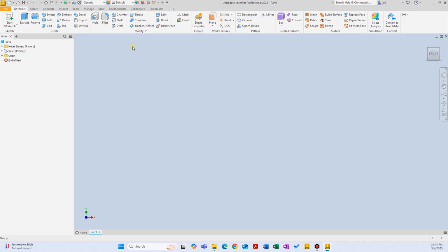Because if you apply a lot of modeling actions and in between you add a bunch of fillets and chamfers, and if you have to go back and modify anything in those features, then those fillets and chamfers may not be applicable anymore. The projected geometries may not work the same way, which would cause a lot of problems, and then you would end up having to go back in the browser tree and find where the problem occurred and spend a lot of time troubleshooting. So that's why always try to finish the design without fillets and chamfers, and then as the last thing to do, add your fillets and chamfers.